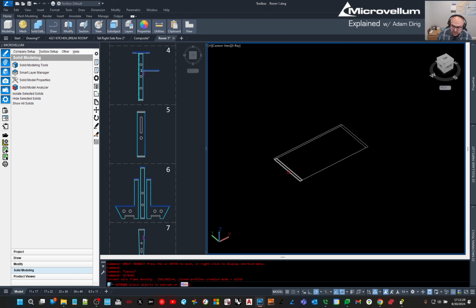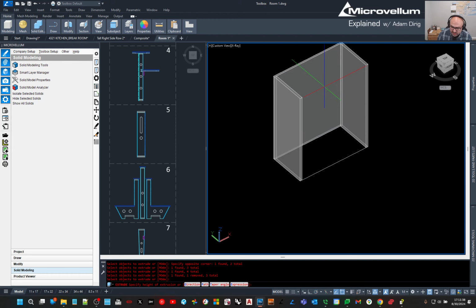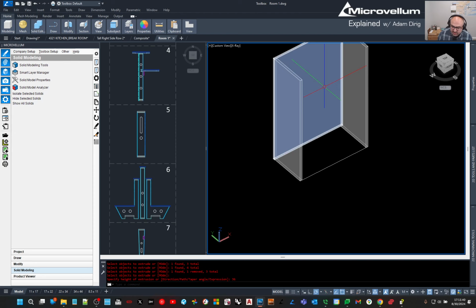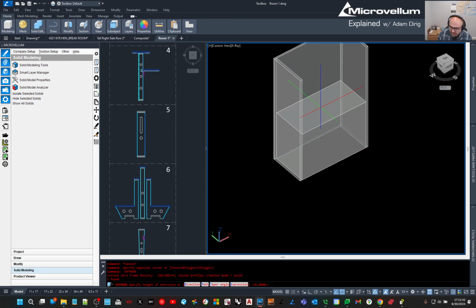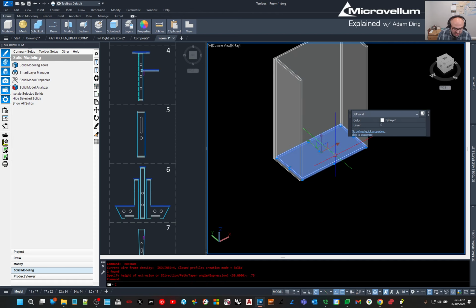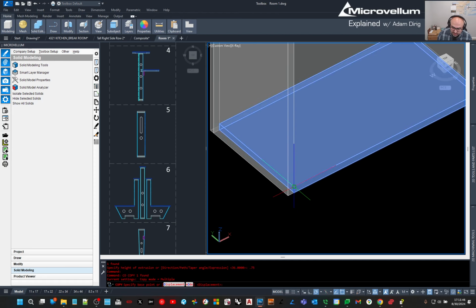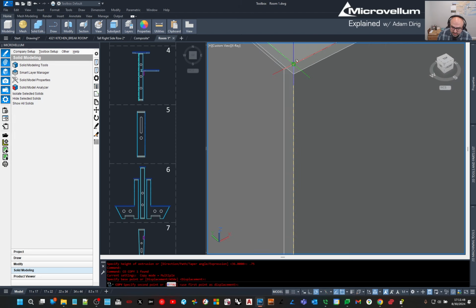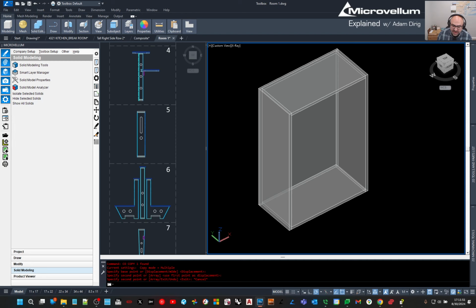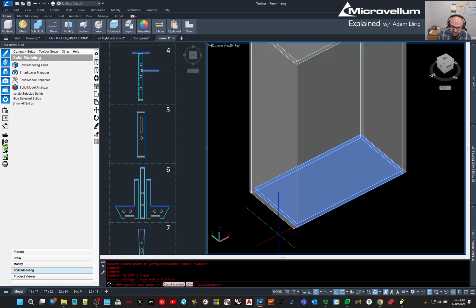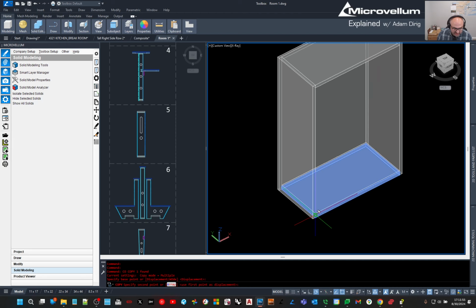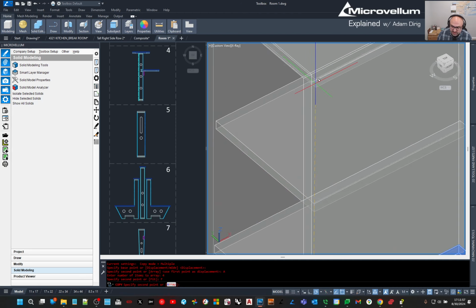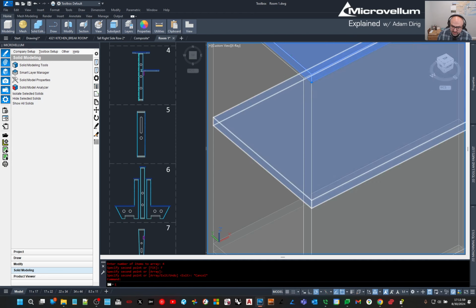So I'm going to extrude. I just typed in extrude and enter. I'm going to grab these 3 parts, not that one. I'll hold the shift button and deselect. And I'm going to say, hey, this is 36 inches tall. This guy here is going to be 3/4 of an inch. Let's copy this up. Now this doesn't have to be just straight parts. It can be curved parts. It can be anything that's going to be a sheet good. So I'm going to copy this. I'm going to say, let's copy array for fit and keep that centered.